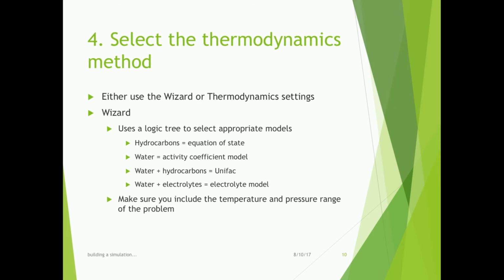Okay, so you've selected components. Now we're going to select the thermodynamics that we use. We're going to use either the thermodynamic wizard, which helps you decide what to use if you don't know anything about your system, or you can specify it to be whatever you want.